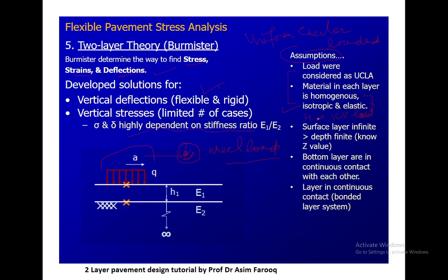The third thing is that the depth is finite. You can see in the figure that h1 is defined, while in the one layer system we have infinite depth. And also the z value, which is the depth, is what we use if, for example, we want to determine the vertical stresses or deflection at any interface or offset.